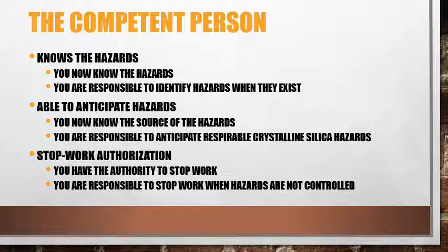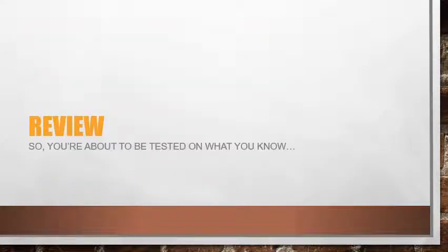And because every GKW employee has the authority to stop work if a hazard exists and it is not controlled: if people are using grinders and do not have the respirator on, you can stop the work and make sure work doesn't proceed until everyone is appropriately protected.